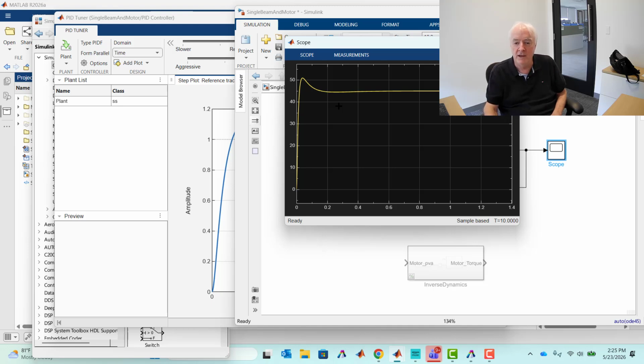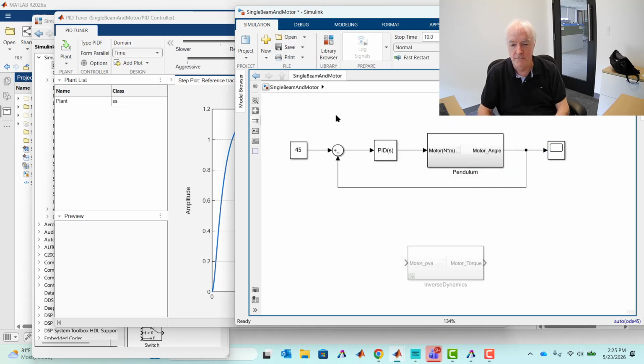And so it's a remarkable thing that PID algorithms can interpret that impossible request and give you what is quite often quite reasonable. But whether or not it's reasonable to you really depends on what your machine's trying to do and what your requirements will be. All right, and so all I really want to do right now is address that impossible request. Right, and in a way I'd say be careful allowing that PID to do that remarkable thing, which is interpret quite reasonably the impossible request.